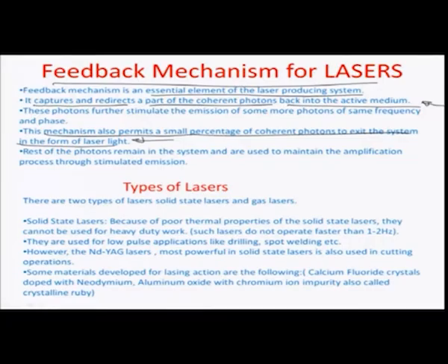There are solid state or gas based lasers. Each of them have their own limitations and shortcomings. Let us talk about solid state first. So, solid state lasers, because of poor thermal properties, cannot be used for very heavy duty work, okay, and also they are not very high frequency. So, they can operate typically with the speed lesser than 1 to 2 hertz. Okay. So, once or twice in a second, that is about how much solid state laser can deliver.